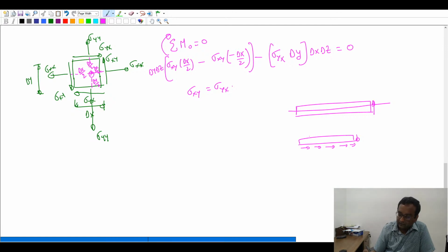This is not a reaction force, and hence in the support reaction there won't be a net horizontal force in a first order analysis. If you do an exact analysis, a straight line deforming into a curved line, there should be a change in length, right? But what we are saying is that the neutral axis has zero strain, right? So there is no change in length at the neutral axis location, which means in the first order analysis there are no secondary stresses due to elongation of the neutral axis. That is free to shorten the beam.